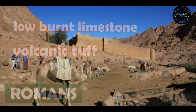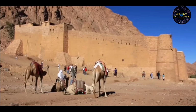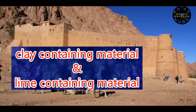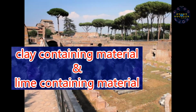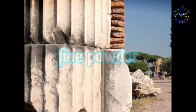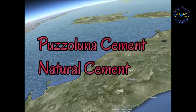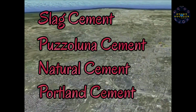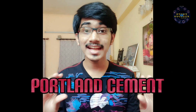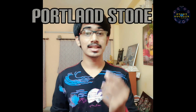Later on, it was found that impure limestone gave birth to better quality cement. Further study revealed that if an intimate mixture of clay-containing and lime-containing materials are fused together, then allowed to cool and finally ground to fine powder, a superior quality binding material was obtained, which led to the formation of natural cement, pozzolana cement, slag cement, Portland cement and others. This cement is so named as Portland cement because a paste of this cement with water on setting and hardening resembled to Portland stone in color and hardness, which is found in United Kingdom.